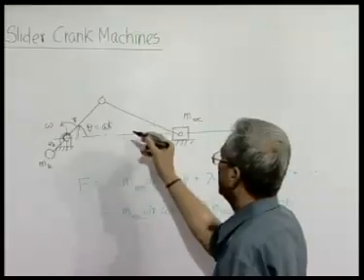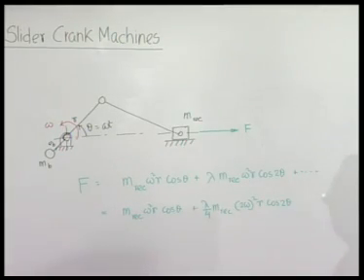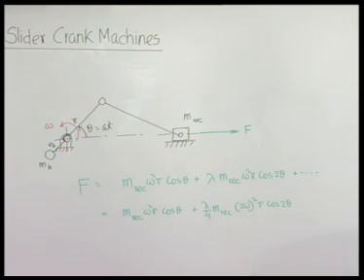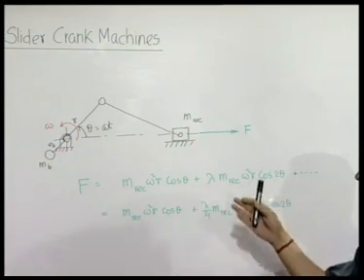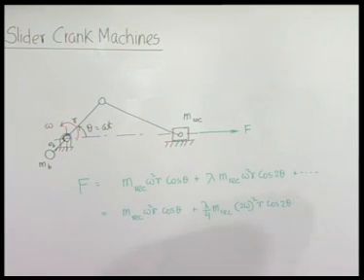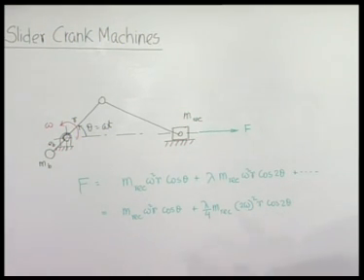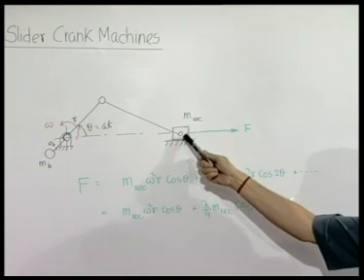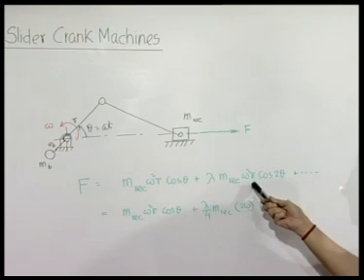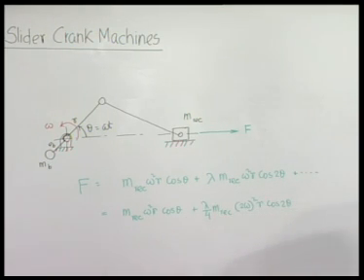If we take theta equal to 0 at t is equal to 0, then these are nothing but harmonic functions of time of continuously increasing frequency. This is also an approximate situation, because we have replaced the actual connecting rod by two concentrated masses, one at the crank pin, the other at the slider pin, which is not an exact replacement, but it does not introduce much error. So, there is a primary component, the second harmonic, fourth harmonic, and so on, that we have seen.